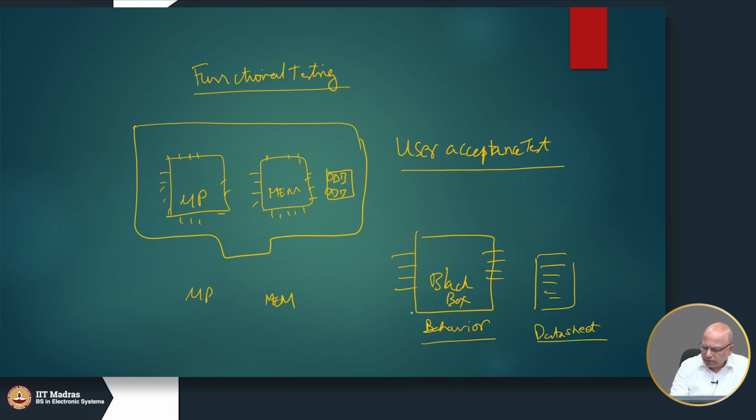For example, if you push the reset button, the program counter is supposed to go to 0 and the address bus will become all zeros. So, that is given in the data sheet. Similarly, it tells you how the instructions are fetched from the memory and how many clock cycles are required to execute individual instructions, all that is explained.